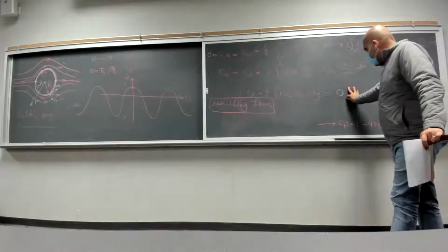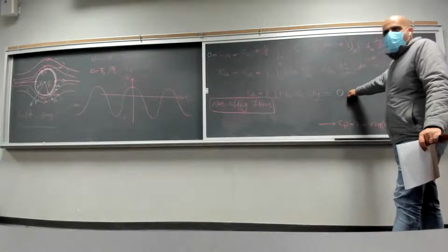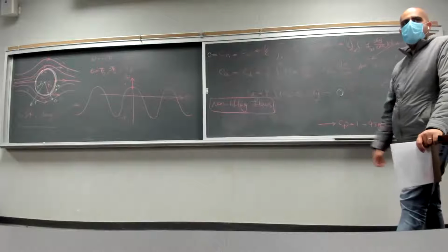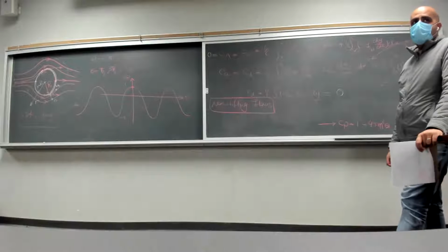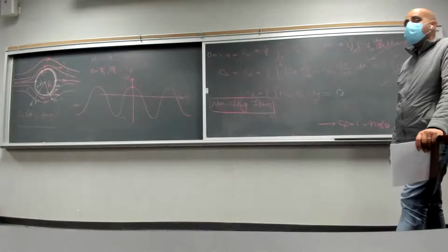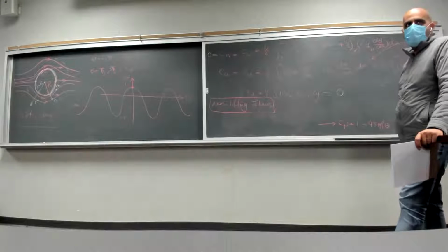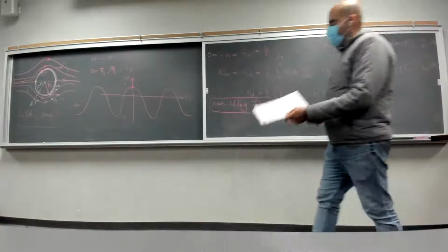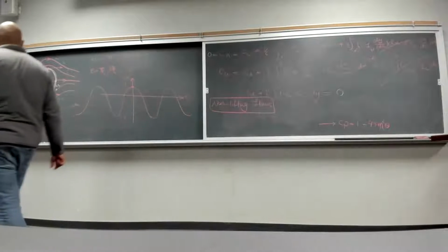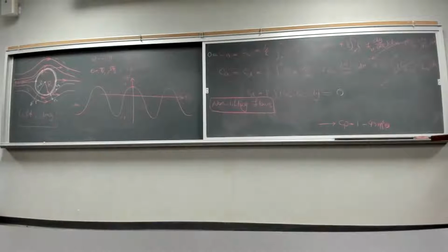But how can we explain the fact that drag is 0 here? Does this make any sense? No, why not? So we are essentially pushing the cylinder, right? There is a drag force. We can see that there will definitely be a drag force. This doesn't make any sense. So what does this mean? This essentially means that the inviscid assumption is definitely wrong here, right? Because we are calculating 0, at least for the drag force. We are calculating 0 drag.